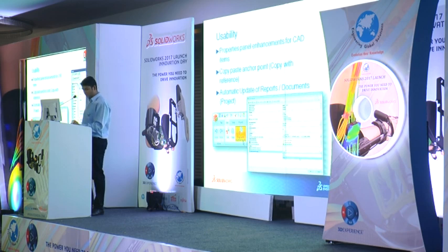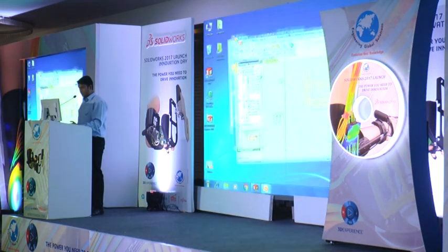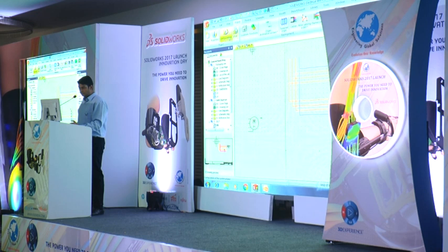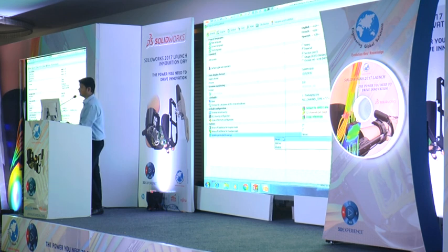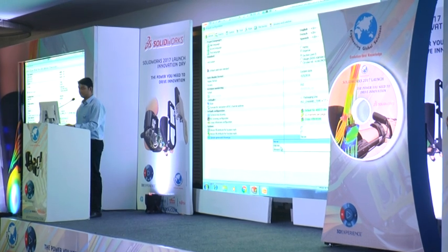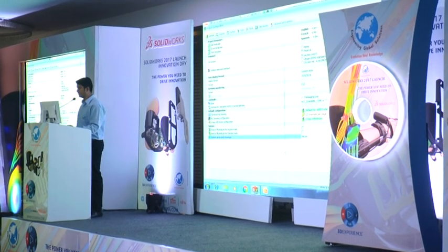So we have that option to keep your reports up to date. We have this update generate drawings option. Under this we can choose never, ask me, and always. If you choose always, the reports get updated always, that is, it will update without asking your permission. Ask me gets your permission, and never means it is updated manually.